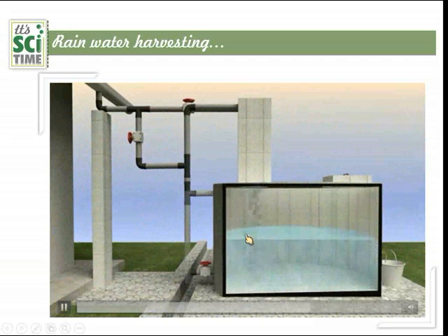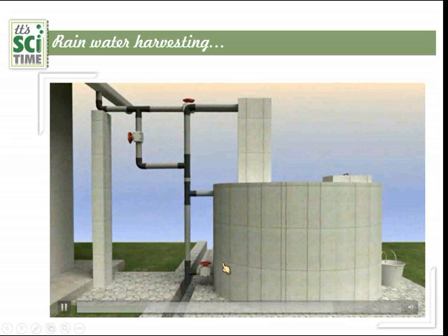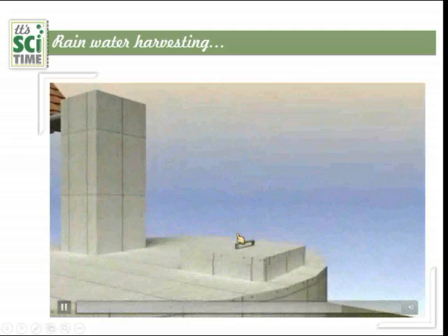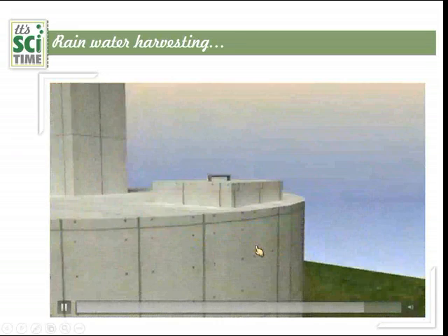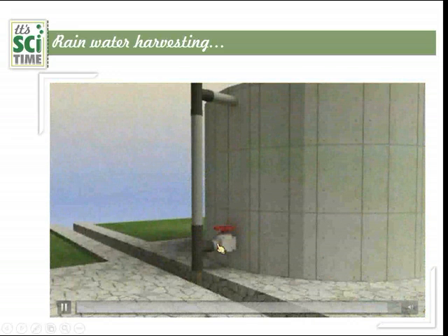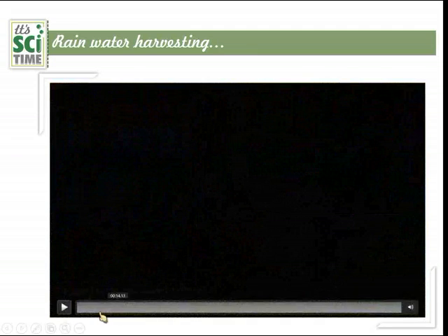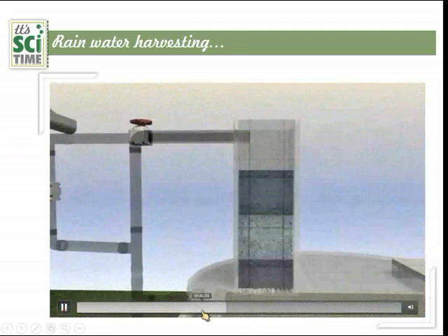In the tank also, if it is overflowing, we can take the water out through this tube. Water overflows through that one. And also when washing the tank, we can open this lid, and also we can add some cleaning agents to this. Water can be taken out from here, and also in washing we can send water out from this outlet. That's how we can arrange a rainwater harvesting setup.